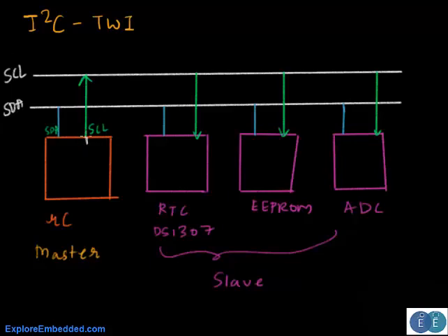They have, say, an FET, and this FET is grounded. There is some control inside, but what you could see is that this particular line, in this case SCL, is not connected anywhere. It directly goes to the SCL of other devices. What that means is this is normally open, or it is called open drain.